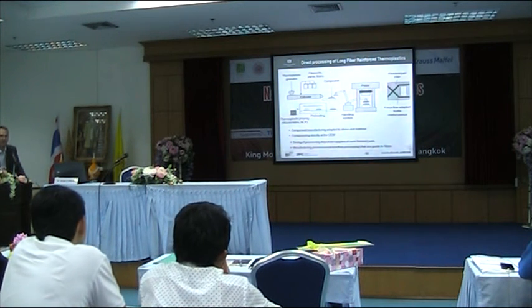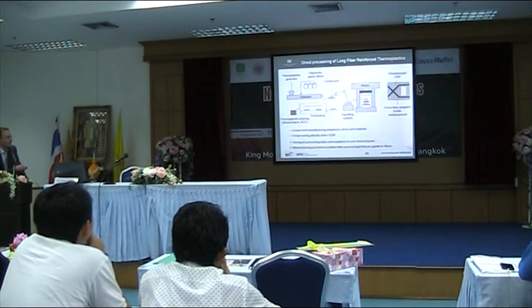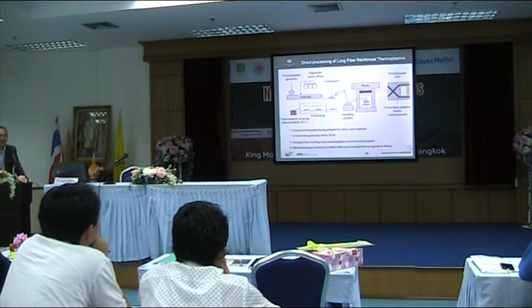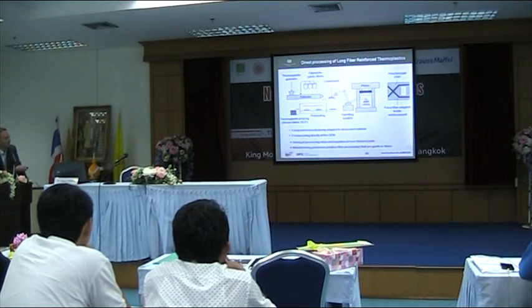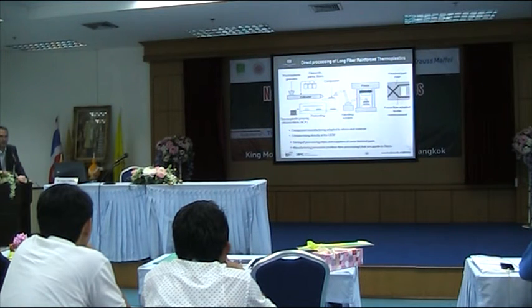So you can adapt the endless fibers to the forces you have on your part. Okay, you have an average fiber reinforcement in the whole part with a random fiber orientation and a local fiber reinforcement with endless fibers.